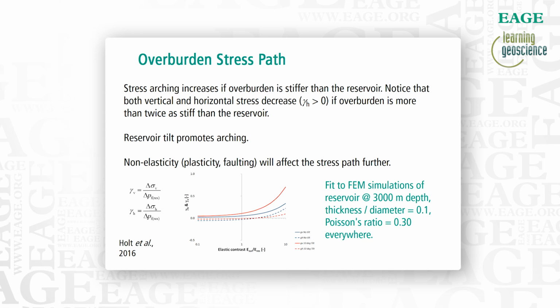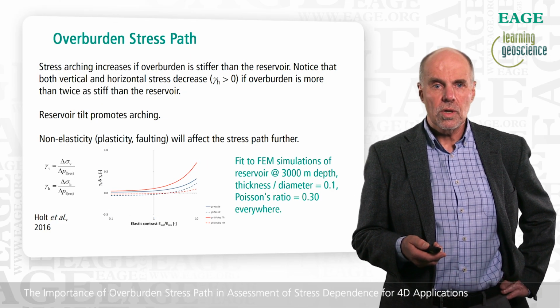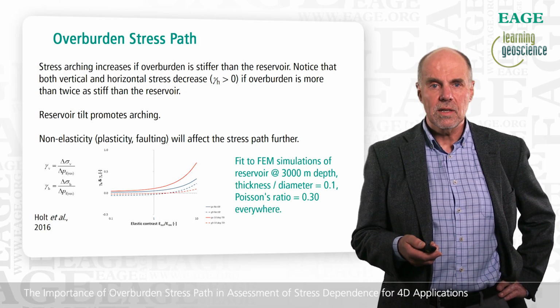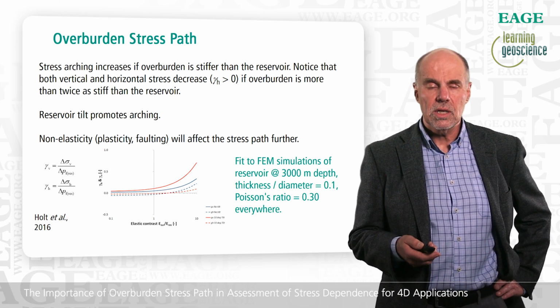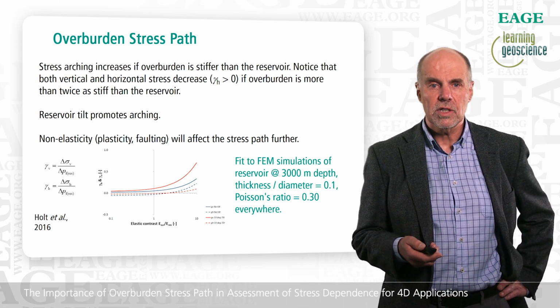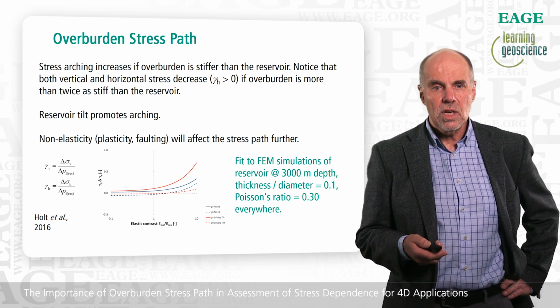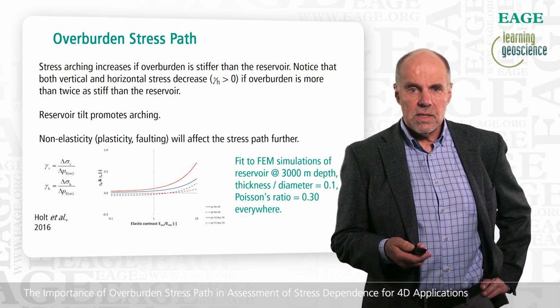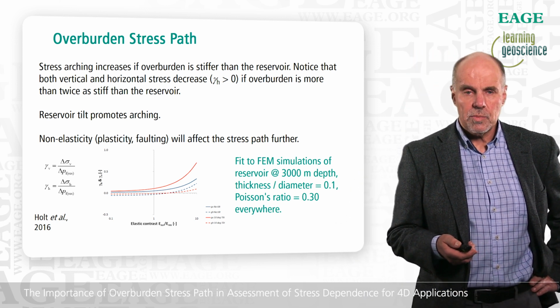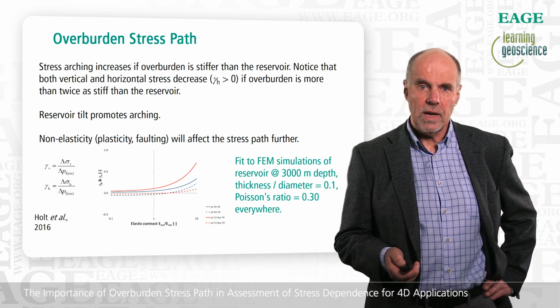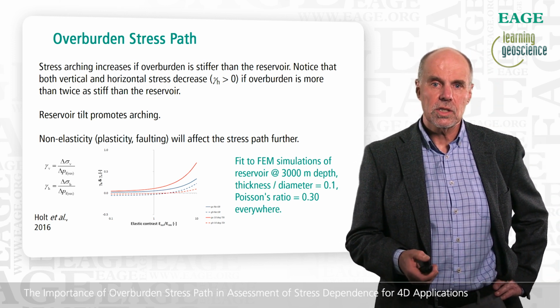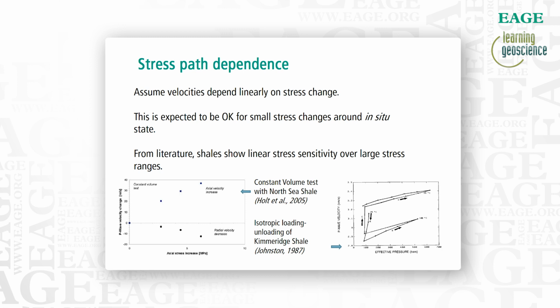The red curves for the gammas show what happens if we have a tilted reservoir, and we see that arching is promoted by reservoir tilt. In addition, non-elasticity, plasticity or faulting will affect the stress path further, but we do not address that directly in this presentation. Now we look at the stress path dependence of velocities, and the main assumptions we will make is